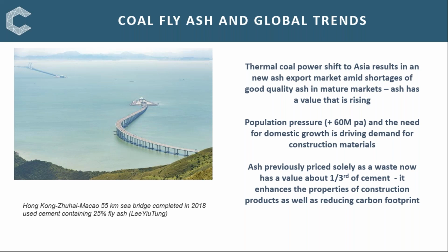The properties of the cement are especially important for the tunnel section. There's an abundance of fly ash available, but not always where it is needed and of the required specification. Stored conditioned ash has to be upgraded before it can be used in most applications. The demand for all construction materials is rising, and that is true for fly ash. And that means it now has a rising value, at about 1/3 of the value of cement at the moment. And cement makes up about 1/7 of concrete.